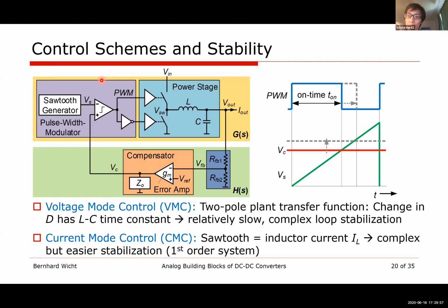Yes. And my second question is, in your experience, what about the EMI of the switching converter? Because I think that for the buck converter, for example, the input current is discontinuous. So how can we deal with that? Do we need to add an external RC filter, or sometimes do we have to add only a single input capacitor?